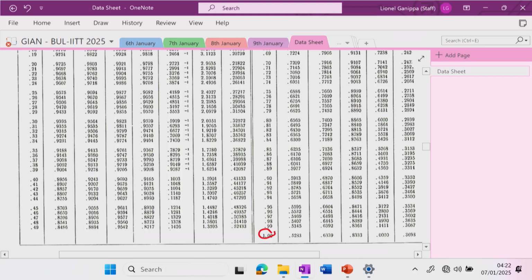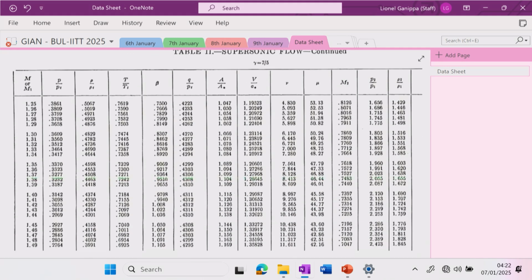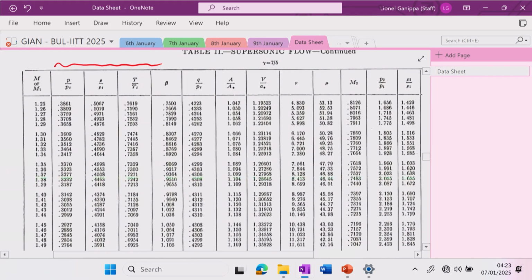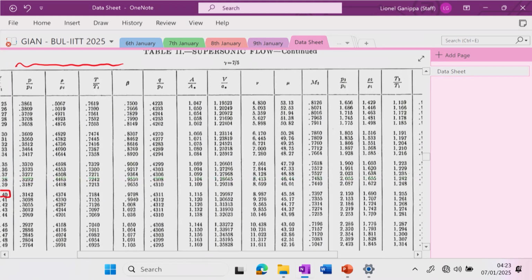Critical condition. So that is the first table. The second table, what you see is the shock table. In the first part of it, you see the isentropic relationships at that particular Mach number, and in the later part, if the Mach number, for example, let's say Mach number is 1.4, after the shock it will be 0.7397.